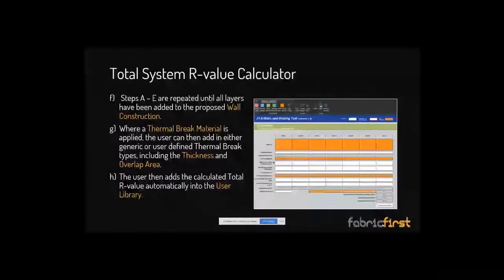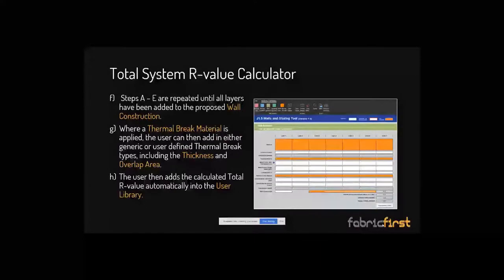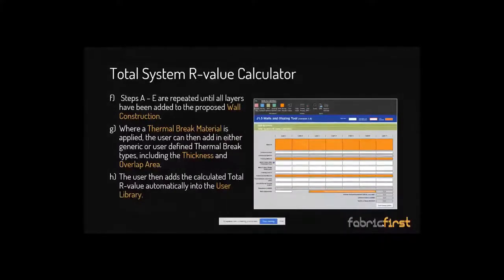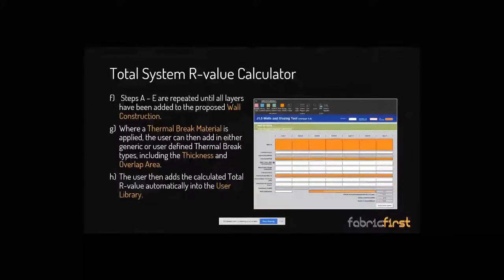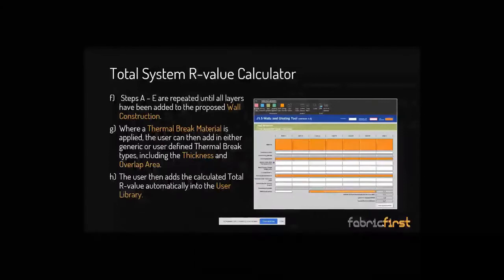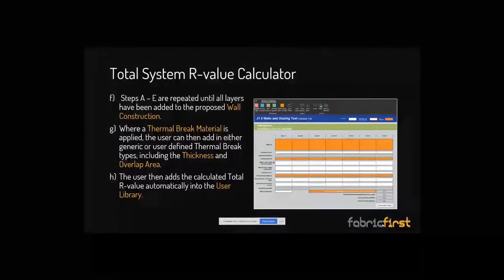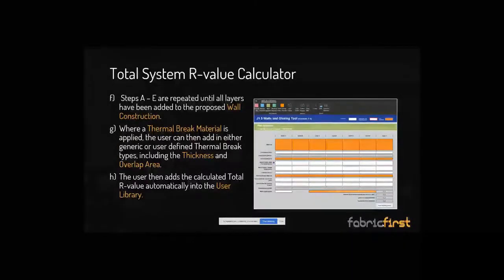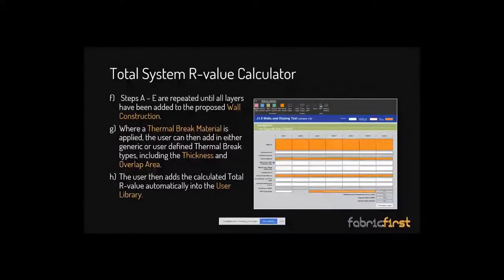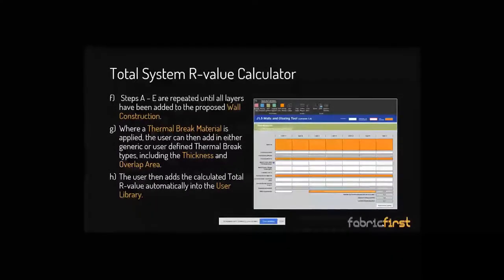And if you were looking at a system that had an efficient 2016 R value of 2.6, throw in that steel, and your system is not meeting the R1 backstop. So steel will break that system, and it won't allow it to meet the backstop. So that's a big change for our industry. Commercial buildings using lots of steel, hospitals, those types of things, it'll be interesting to see how they manage that. That's not to say there's no way for steel to be used. There is. We can use thermal breaks.